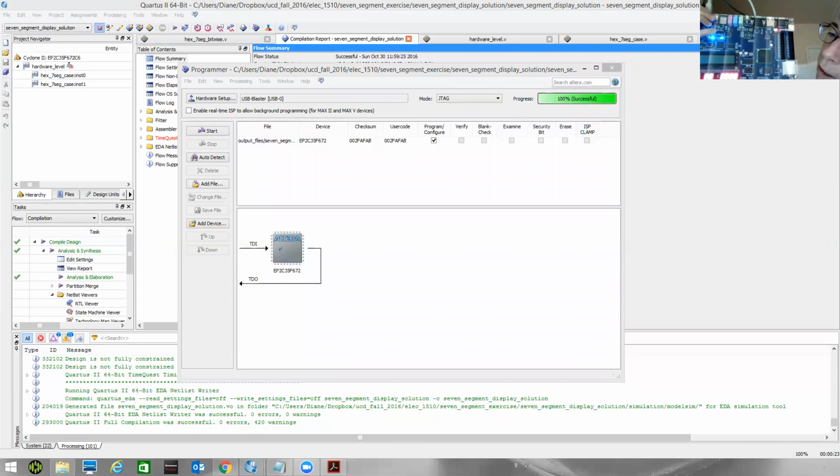So we just enabled another display then by creating an instance of the module and saying we want to show the same outputs. I could wire different switches to that so that we could show different outputs on there. But what I'd like to do next is I'd like to have a way to just turn an LED or 7-segment display completely off using an enable signal.